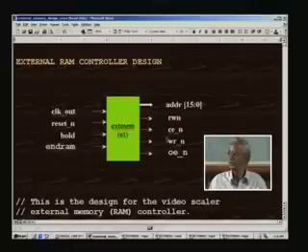In addition to this, we need 2 sets like this for the 2 RAMs, and these signals are CE, which stands for chip enable. If you have 2 RAMs, naturally CE1, CE2 you can have. Similarly, this is a write signal for the external RAM, and this is the read signal for the external RAM. OE is output enable. Normally the nomenclature used in most of the memory vendors is precisely this.